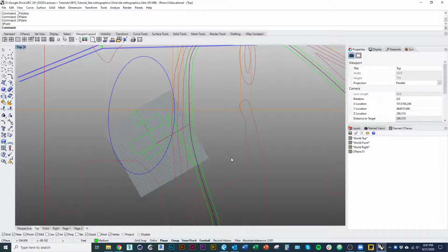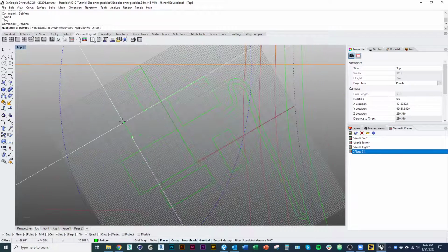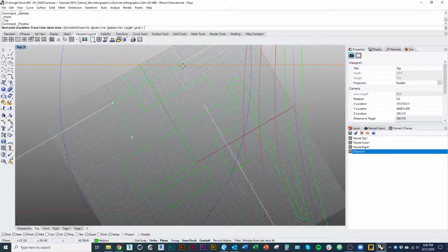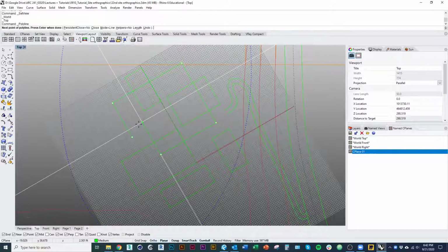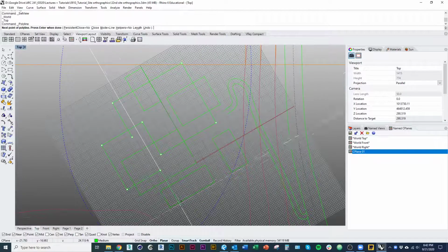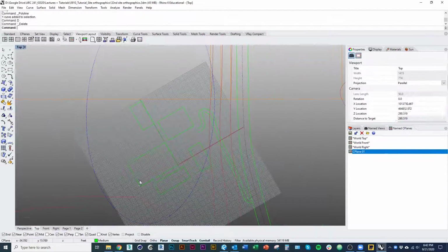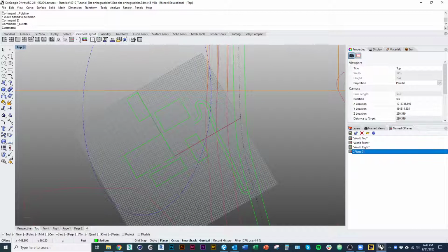Okay. And so basically, every time you reset your viewport, you'll notice that your C-plane will reset, right? So I just re-entered top view. Obviously, my C-plane went back to just normal X and Y. All I got to do is in the named C-plane panel, hit that button, and it'll switch me back. So now whenever I'm working, I'm already oriented to that plane, holding shift right now to snap to ortho. And you can see every line that I draw is kind of oriented along that plane.